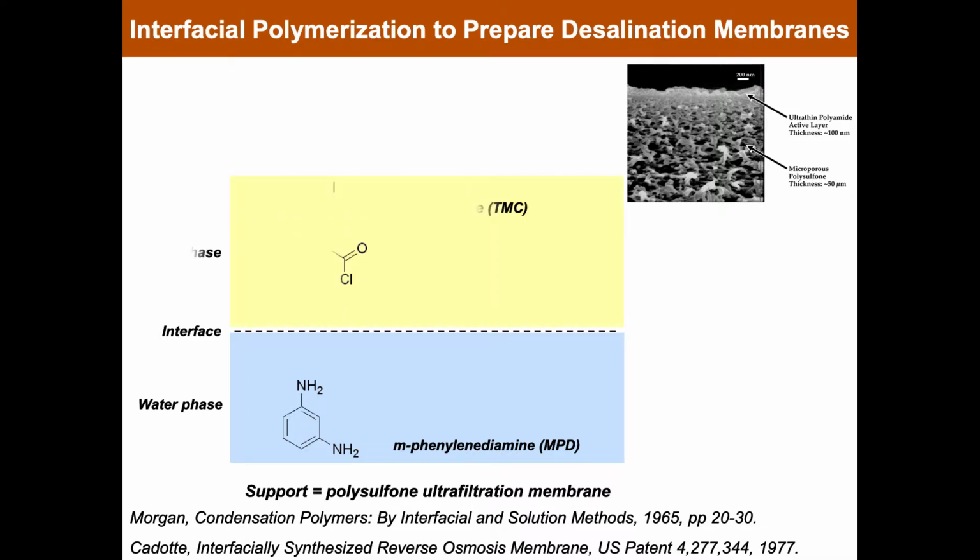a layer of oil or an organic phase is put on top of this membrane, and it contains a compound known as trimesoyl chloride. The trimesoyl chloride has almost no solubility in water. The metaphenylene diamine, while it's water soluble in the concentrations it's used, has a bit of solubility in the oil phase as well.